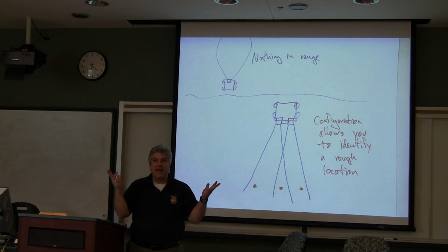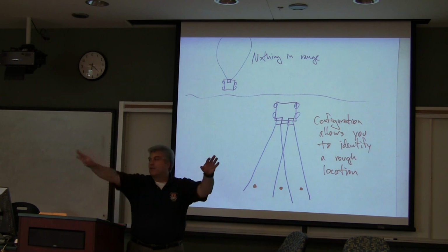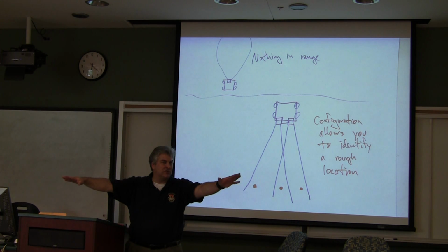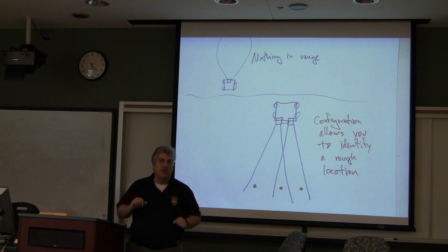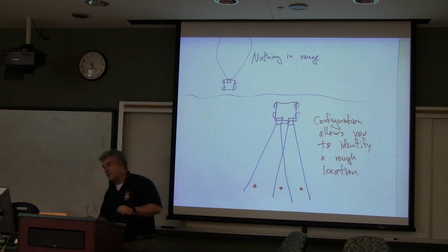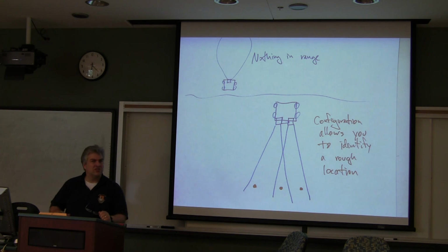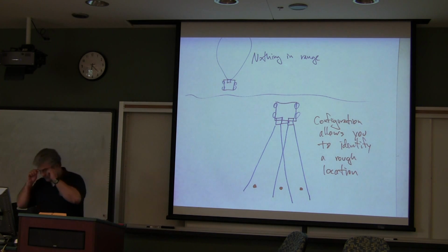You might have too much noise out there, so that one transmitter here will actually be picked up by this transmitter receiver over here. So you have to make sure that you are only doing one ultrasound at a time. And I think I mentioned this, the way to fix that would be maybe having two different ultrasounds with two different frequencies.